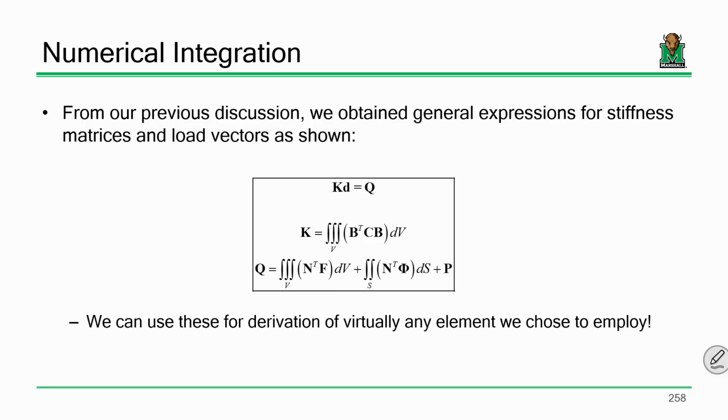Before, it was literally take the bar, yank on it, record its resulting forces. Now we've got a little bit of a different approach. We actually integrate these assumed displacements and their respective functions over the volume. Is it a lot more math? Yeah, but one of the nice things about it is that once you do it once, you never have to do it again. In other words, when you all start using programs like Abaqus or ANSYS or LS-DYNA, ADINA, whatever, you'll hear a lot of finite element programmers refer to what they call a library of elements.